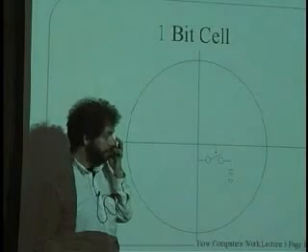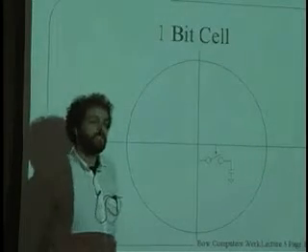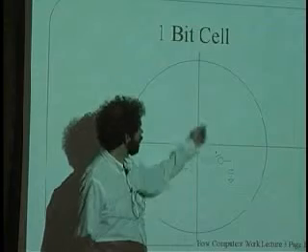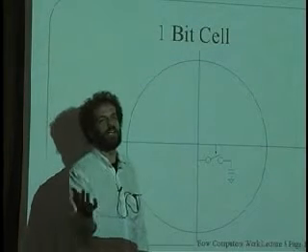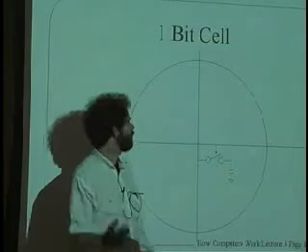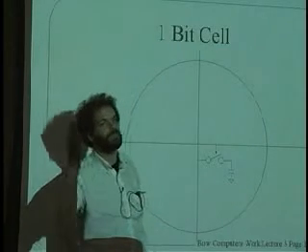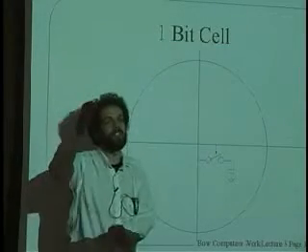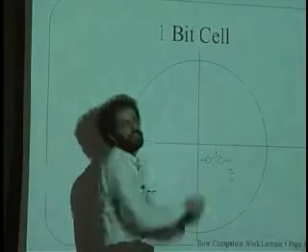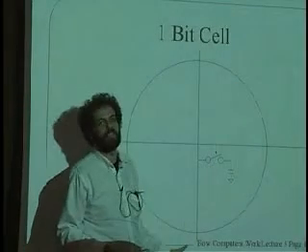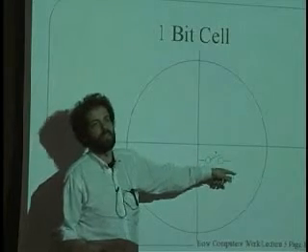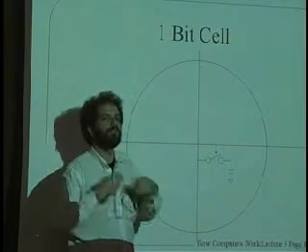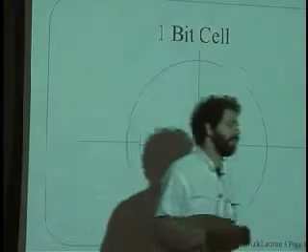And if we want to read whether or not there's a 0 or a 1, it turns out that reading that is a destructive thing. In other words, we're going to close this switch, and we're going to suck all the energy out that we can, and we're going to measure how much we got. And in the process of doing that, we will have erased the bit. But that's okay, because we remembered what it was, and after all, we have to write it back anyway. So then we'll restore it to either a lot of energy or no energy, and we'll go whoosh and write it back here. So every time we read a bit from something like this, we actually write it back also. And furthermore, every 1,000th of a second, if we haven't done it, we read and write just to keep it refreshed and up to date and either high or low.